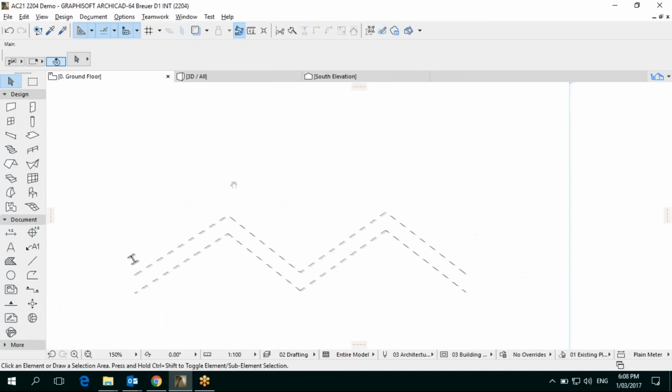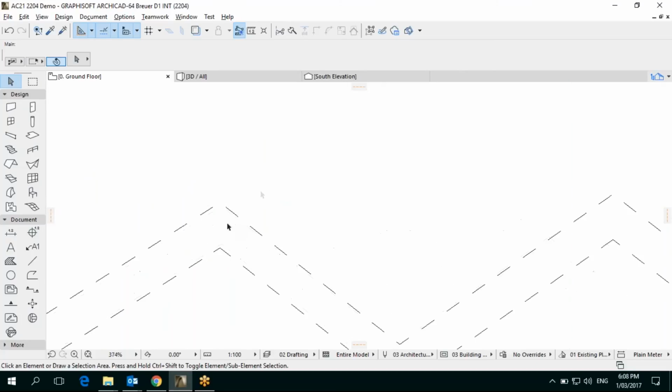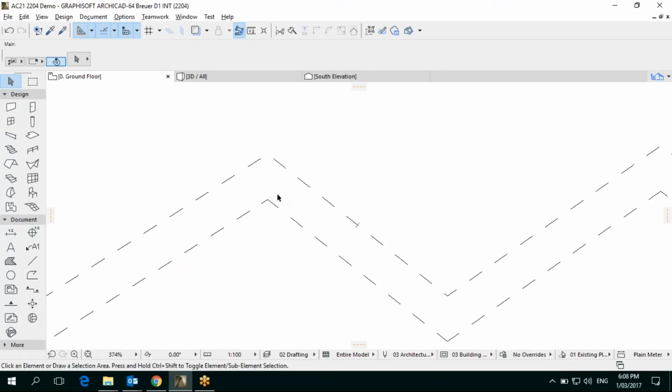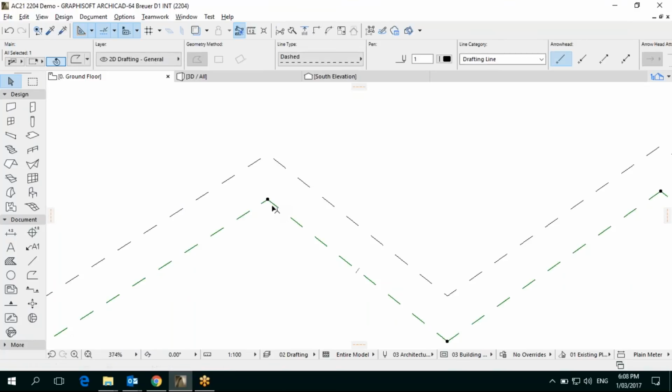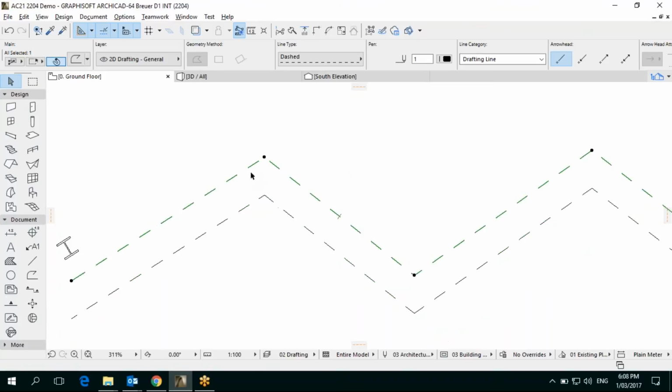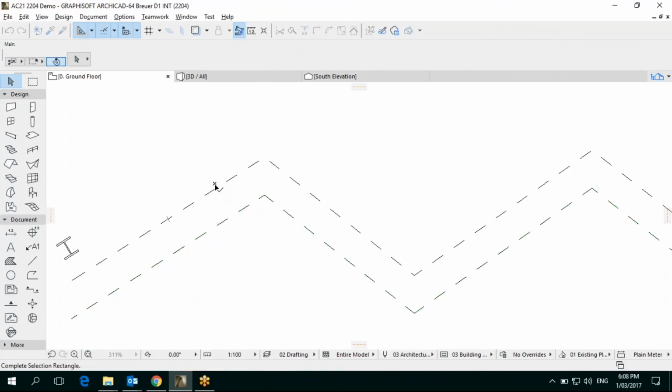The second feature is regarding the 2D line dash handling. Here I have two polylines using two different methods. For all construction elements, we now use the new method, which is this one, to always show lines within corners. You can see the old, legacy method basically runs the dashed line over the entire segment, from start to end, but the new one is based on each segment. So this is distributed over that segment versus the entire length of the first one.